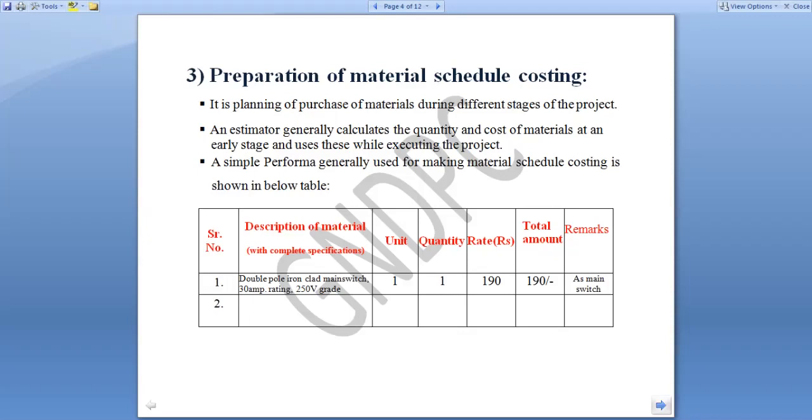The wire for wiring the building is then calculated sub-circuit wise, and this too is done on the basis of the installation plan. And in the last, the total length of the earth wire required is calculated. Now, a few appliances like switches, sockets, outlets, then switchboards, lamp holders can be directly calculated from the installation plan.